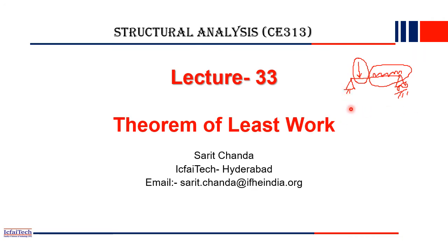Just by drawing the bending moment diagram and the M by EI diagram, we discussed three methods to calculate the slopes and deflections using the geometric method of structure analysis. But if many loads are acting at a time, maybe a UDL or UVL, uniformly varying load, or multiple point loads, then drawing the bending moment diagram and the M by EI diagram will be a little bit hectic. To overcome this difficulty, the energy method is very useful.